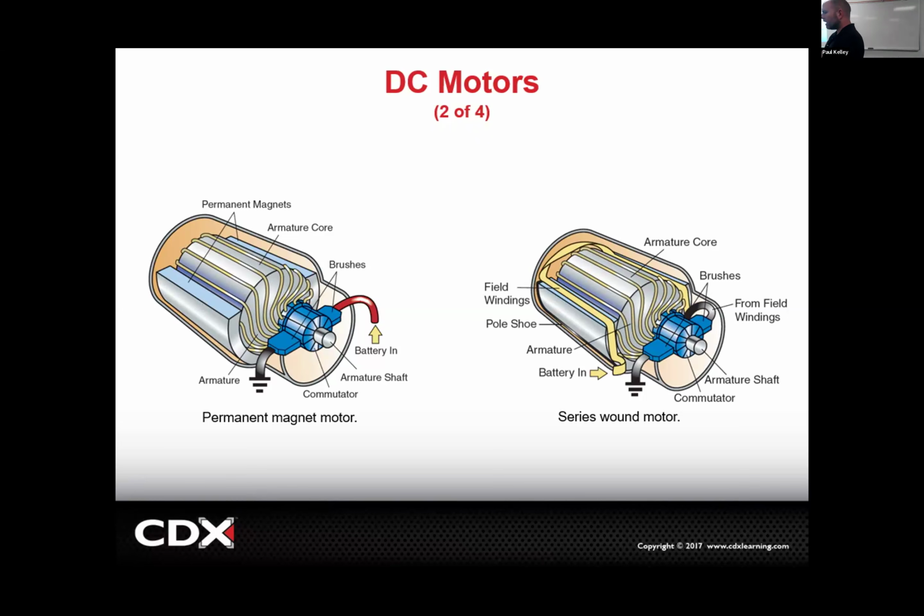How long can you get by? I mean, as long as you're willing to bang on it, it'll probably keep working. But, okay, unofficially, if you look at this starter, this part actuates the solenoid. This is the actual motor part, anywhere on this round piece. However, they're a lot more sensitive now when they have these permanent magnets. So if you hit it too hard, you'll break a magnet, and then it can't be remanufactured.